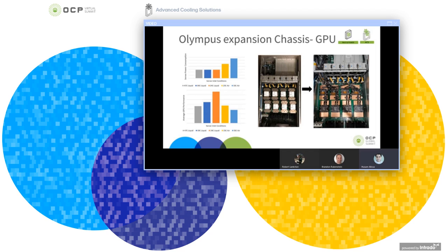Similar to the CPU case, we ran an investigation whilst running neural network type workloads provided by the Microsoft GPU team. In both charts, light blue and yellow columns represent the air-cooled permutations for cases of 35 Celsius and 25 Celsius air respectively. Orange, dark blue, and gray bars show data points for the water temperature sweep. The server power consumption graph shows the effect of reduced server power when using liquid cooling due to significant fan speed reduction and reduced leakage current.